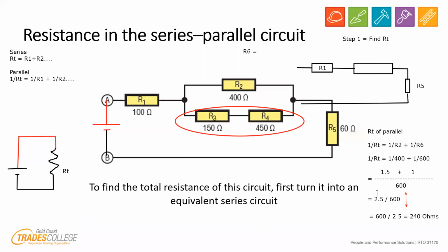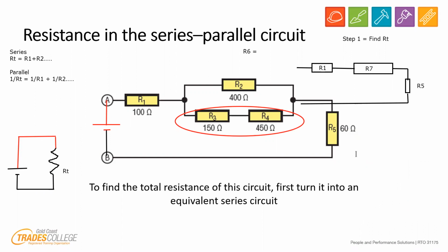All right, now we've used all the resistor numbers so far, so I'm just going to use resistor 7. It doesn't matter one bit. You can use whatever one you want to use. So now I've simplified the circuit again. Now I've got 1, 2, 3 resistors in series. Now we remember from our previous class that resistors in series can be simply added up. All right. So once again, let's get our equation right though.